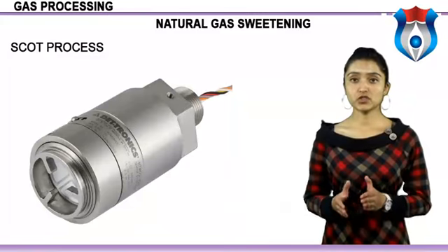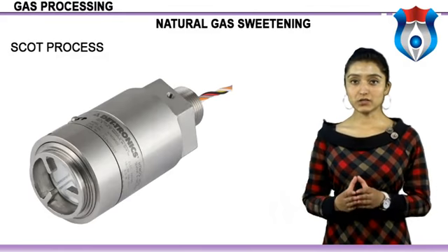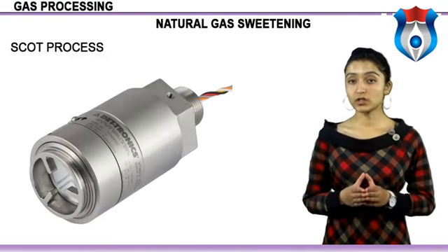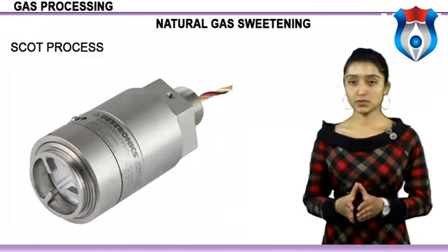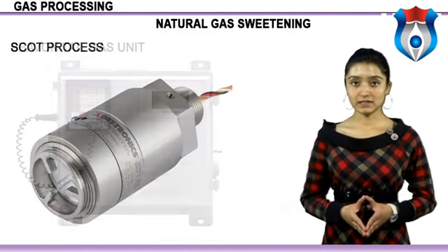The rich amine is stripped in a conventional manner and the H2S rich stream is recycled back to the front of the Claus plant. The Claus plus Scott processes combine to remove 99.5% of the S.